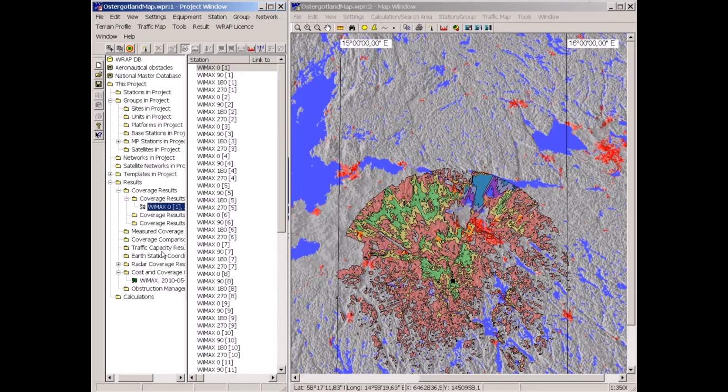So this is a very useful calculation that a commercial operator may like to make available on his website for each base station or network, because this can be done for all base stations, and use another function, multiple calculation, and then show maximum required antenna height, it's called, and then it shows in every point how high an antenna a client is required to connect to just one base.